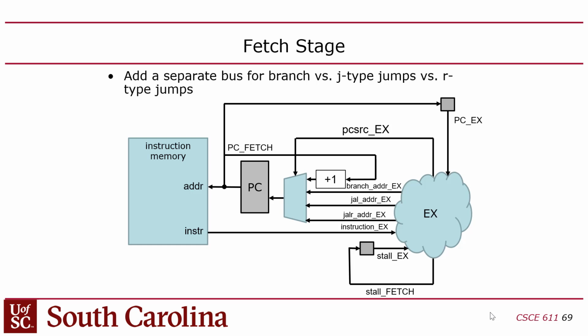Now, how do you do that? You can't really do that because by the time you do that, again, you've already fetched the next instruction, right? You're fetching instructions from a synchronous memory. So there's no time to slip in a no-op because a synchronous memory takes a whole cycle to read, right?